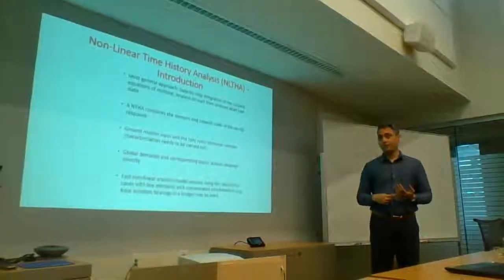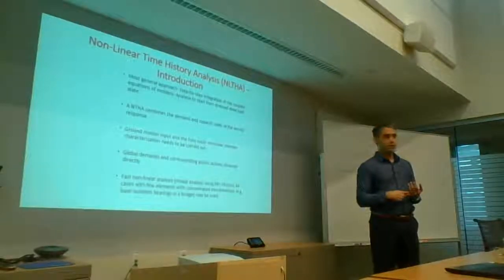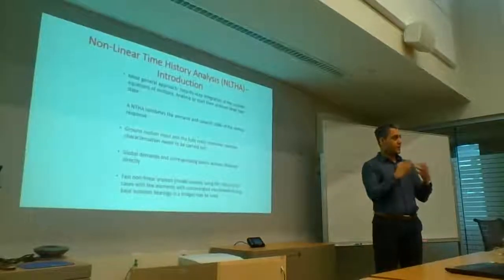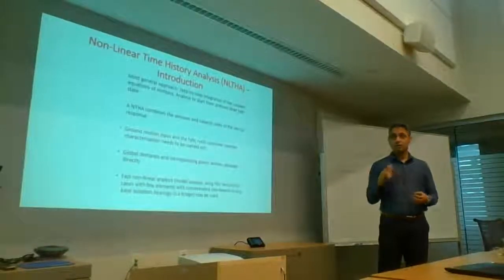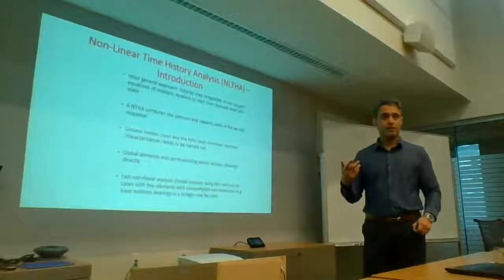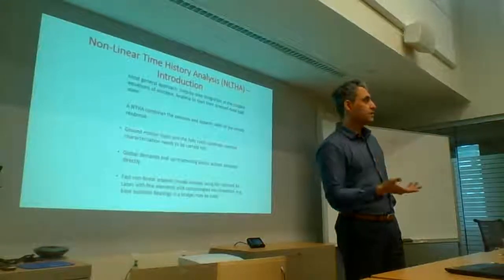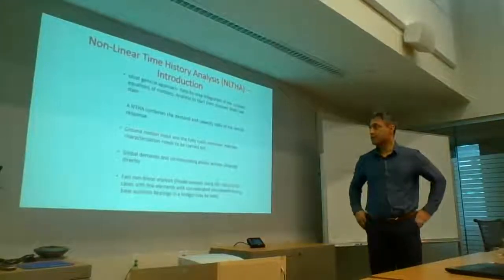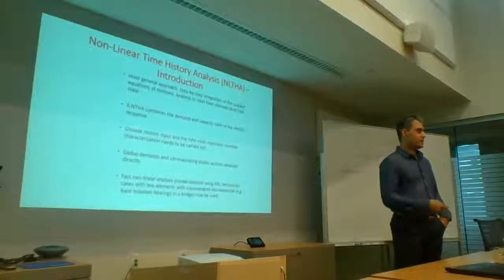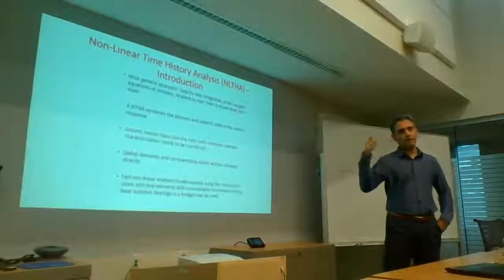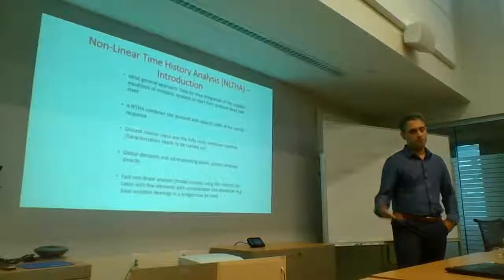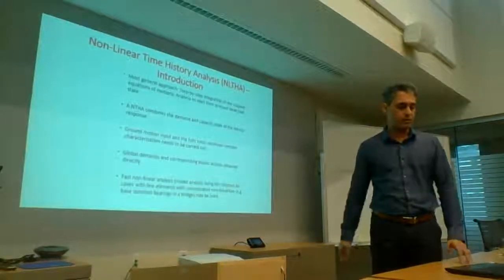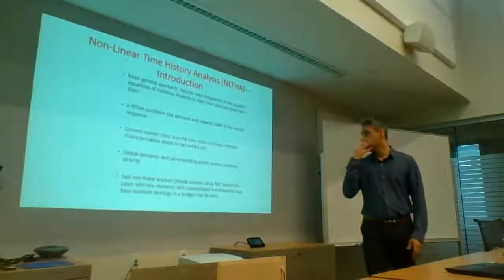When we run the nonlinear time history analysis with all the material models in there, degradation, what have you, real-time analysis, no need to do any kind of statistical combinations, you are going to get the final picture. The demand and capacity are now intertwined. So right away you see your displacement is this much, your strain is this much, your rotations are this much, so you can directly compare it. There's no more processing in terms of, okay, I'm going to now divide this rotation by that much. It's just happening right away.